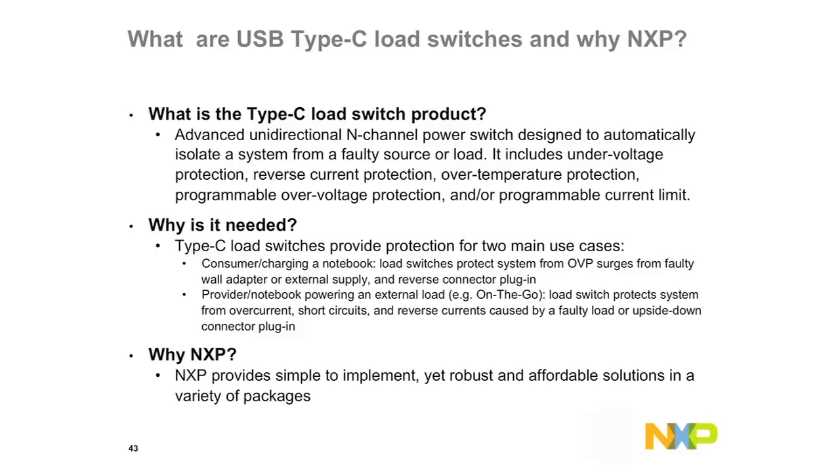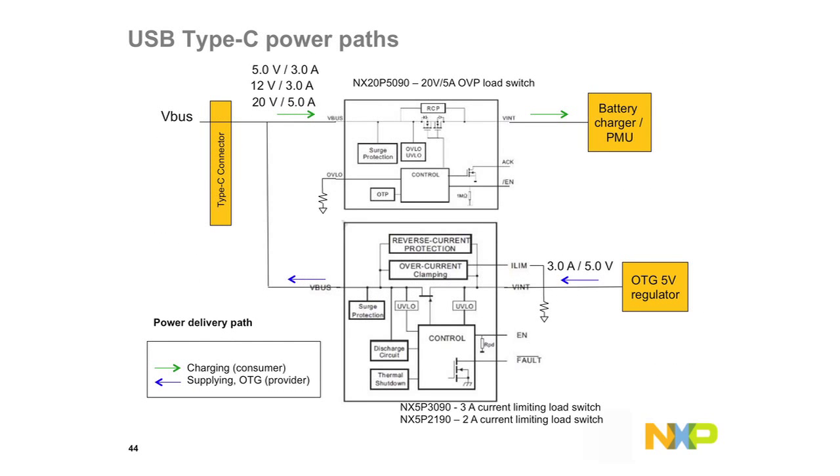So as you know, load switches are basically integrated FETs with security features built in. Depending on the application, it could be OVP, overcurrent protection, reverse current protection, or over temperature protection. But when it comes to Type C, there are 2 main use cases that I want to touch upon.